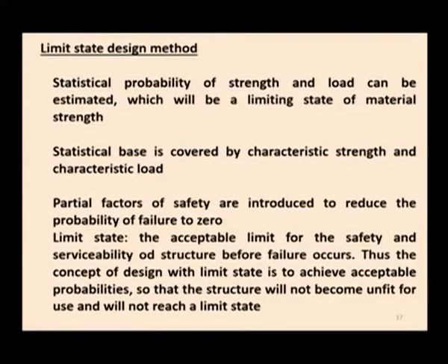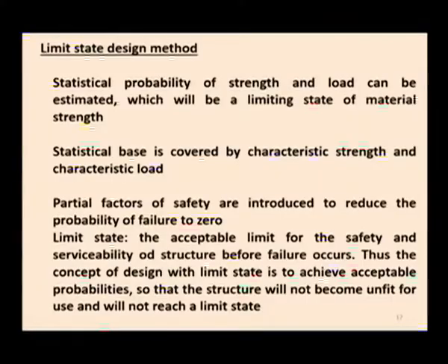The concept of design with such a limit state is to achieve acceptable probabilities, so that the structure will not become unfit for use and will not reach the limit state. Though structures or RCC elements can be designed to their ultimate loading conditions, a certain factor of safety has been added, called a partial safety factor. A structure designed to its ultimate load starts failing when the stresses in the materials reach their respective ultimate stress conditions. In order to avoid that failure, a factor of safety is added, called a partial safety factor.